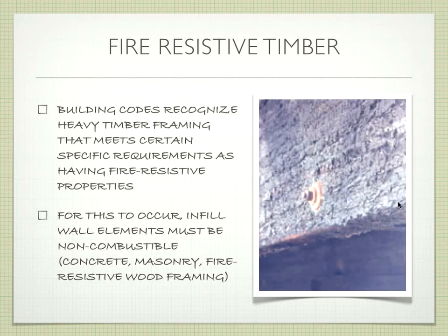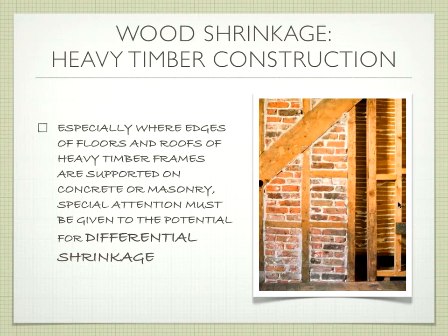Fire-resistant process. So for this to be considered a fire-resistant material, the infill walls, the floors and that sort of thing, still have to be made of a non-combustible concrete, fire masonry, that sort of thing. Okay? So the infill panels, let's see if I have a picture here. The infill needs to be fire-resistant. So you have your heavy timber frame, the infill is fire-resistant material like brick. That's when it is a truly fire-resistant building method.